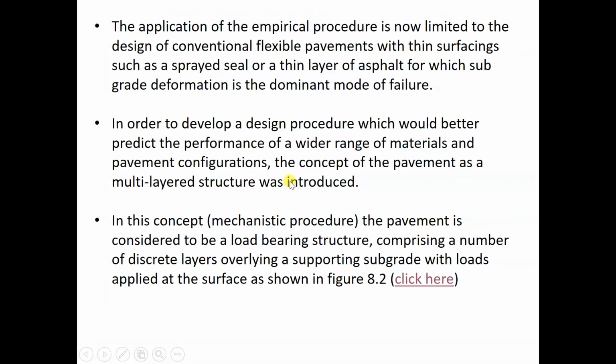So we consider the pavement as a multi-layer structure. In this concept, which is called the mechanistic procedure, the pavement is considered to be a load-bearing structure comprising a number of discrete layers overlaying a supporting subgrade with load applied at the surface, as shown in the figure.